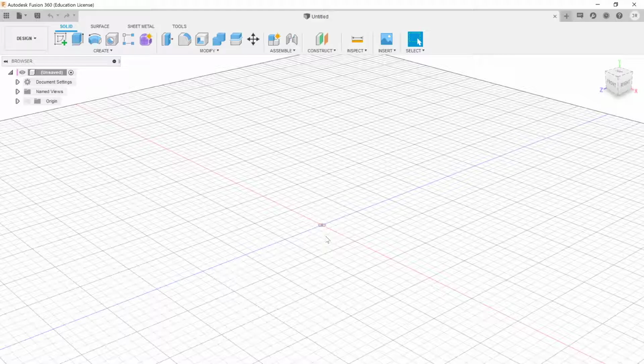So let's first, and we're going to do something very simple. We're going to make a circle in our original drawing. And then our second drawing is going to be a square, and the goal is going to be to kind of stretch and make a 3D object by blending through both sketches until we have a new kind of exotic result. So let's go ahead and do that.